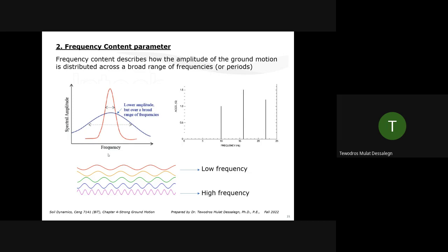One is the reciprocal of the other. So the larger spread you have, the larger possibility that it can damage more structures. If you have a very narrow frequency input motion, it can damage only buildings within this area. It doesn't have that much frequency content, and you may miss out.